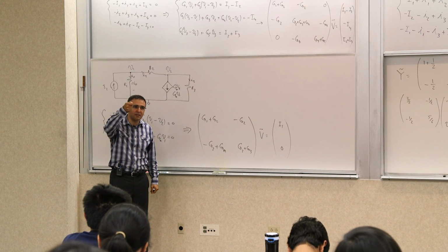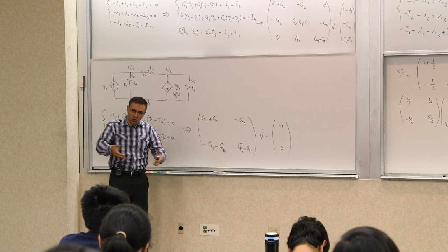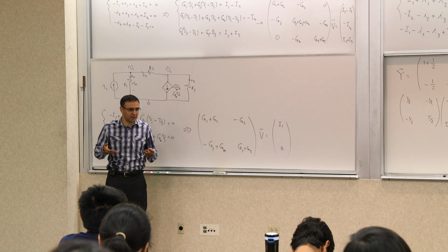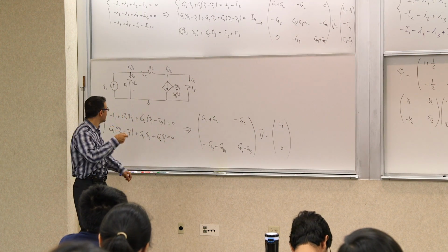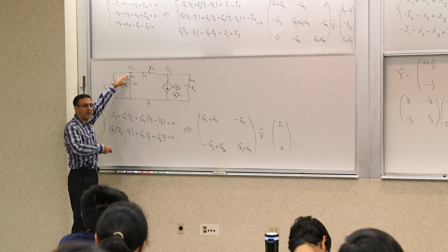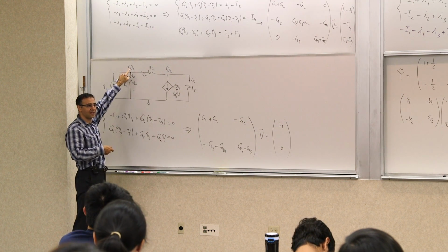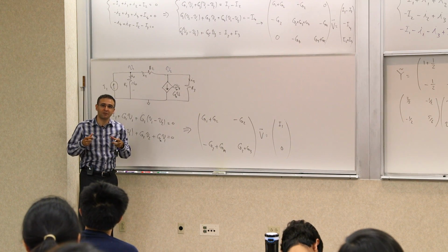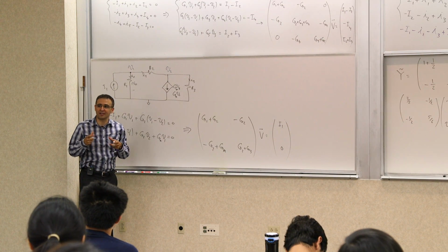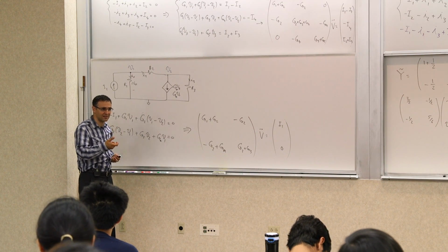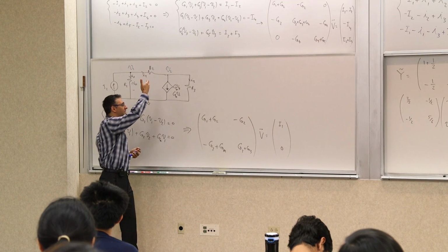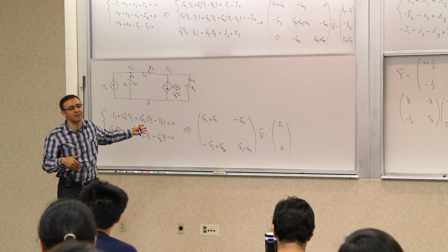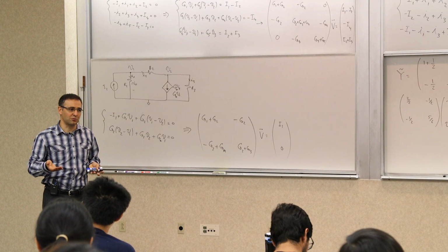If I apply an electric field to it, I can get more or fewer electrons in that channel, or charge carriers. So that's the gate. That's this terminal, controlling it. If I increase the voltage on that terminal, I get more charge carriers inside the channel, which means my resistance is going down. So I produce a smaller resistance, so that can carry more current. So that's one way to approximate this, for example. Again, there's a lot more to it.